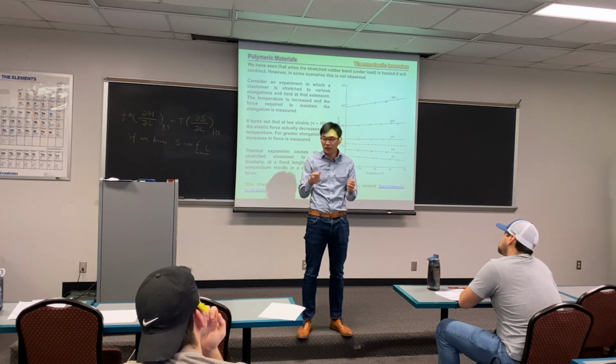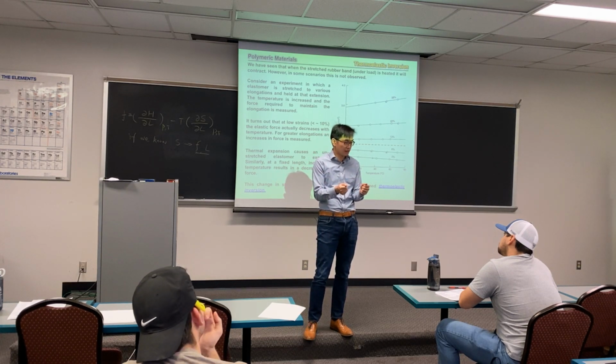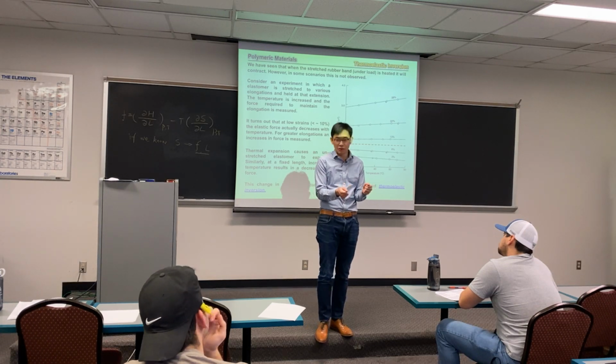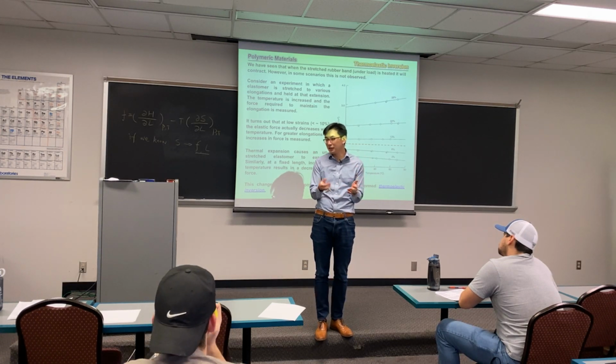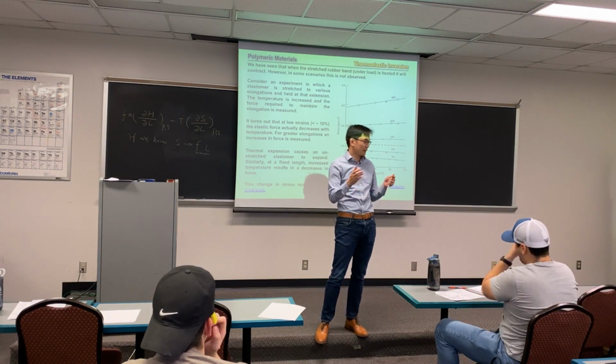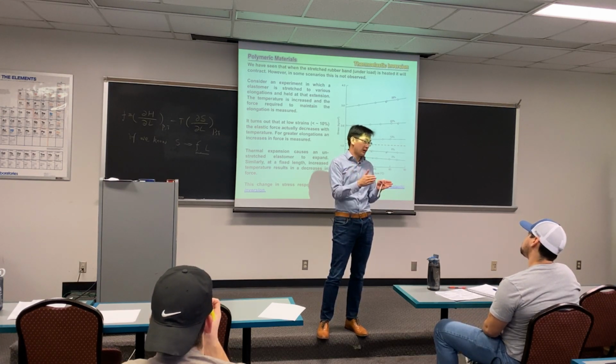Now imagine we hold the clamps and start to vary the temperature, using an environmental chamber. As we mentioned, a difference between a metal and an elastomer is that when you heat the elastomer up at a constant weight, it will retract, right? We have talked about that.